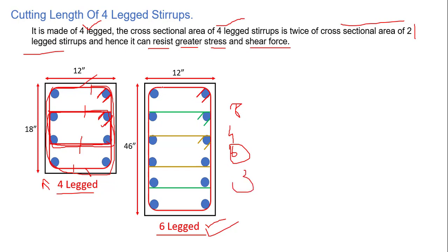Here in this case you can see we have 1 master stirrup that is external. Let me mark this one, it is external. This is going to join this bar, this bar, this bar, this bar. It is going to support these 4 bars directly with these edges. And we have another stirrup, that is this stirrup. It starts right from this position up to this position.